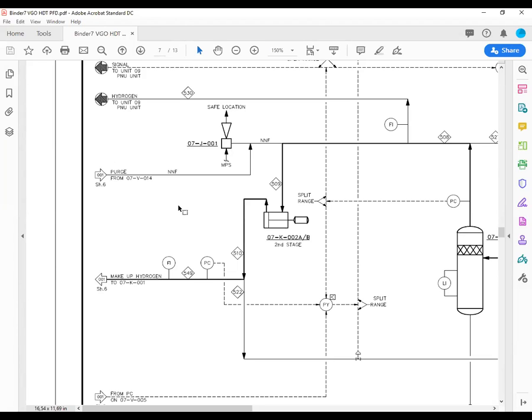No, it is possible, but you have to follow a very appropriate procedure. They recommend to do it not in the reactor itself, but to unload it and send it to a specialized company to make the regeneration.